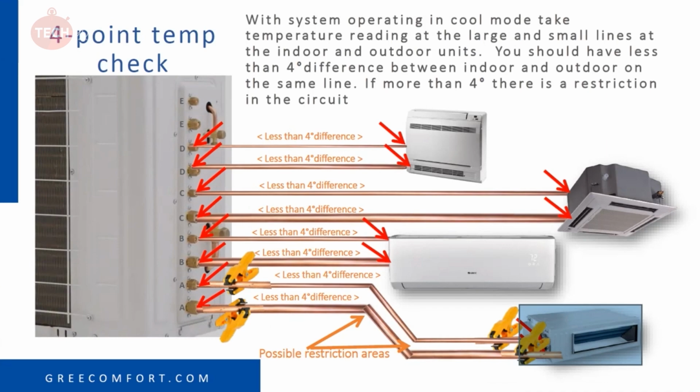You want to have a temperature probe on your suction line on tube A, inside and outside. Let that unit run for a good 10 minutes. There should be very little to no difference from inside to outside. Again, anything more than 4 degrees, we definitely have a restriction in there. The shorter the line set, the less than 4 degrees. So I tell people, if you have a 15, 20 foot line set and you have 4 degrees, we still may have a slight restriction. It's just on a longer one, but on a shorter one, you should have even less difference, like a 2 degree difference from inside to outside on the shorter ones.